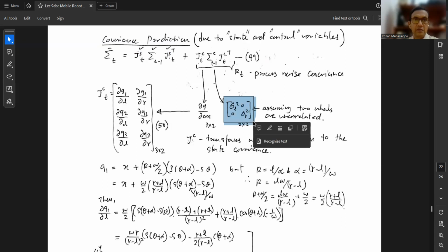Do the testing: turn the left wheel 100 times, measure the distance, get the error. Do the same thing for the right wheel. Take the right wheel out of the robot, turn it 100 times, measure the distance, get the error, square it, and get the average. So then you have sigma L, sigma R, the standard deviations, and squaring them you have the variance. It's a constant for a given platform.